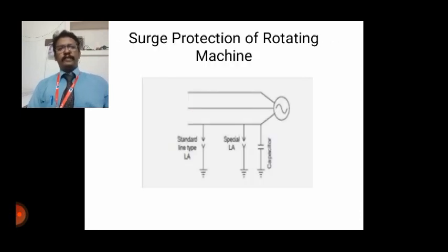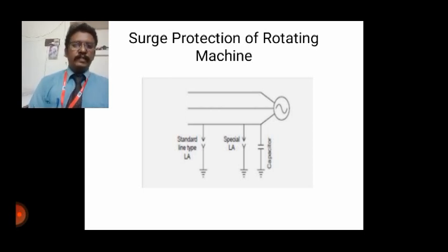Even simply we can use it for arresting that particular low voltage. Normally, a rotating machine is less exposed to lightning surges as compared to the transformer, because the transformer is exposed to the atmosphere. Because of the limited space available, the insulation on the winding of a rotating machine is kept to a minimum. The main difference between the winding of a rotating machine and the transformer is that in a rotating machine, the turns are fewer but longer, and are deeply buried into the stator slots.